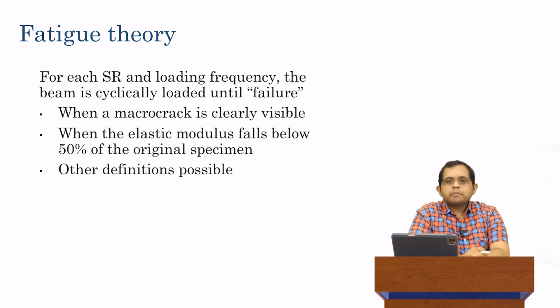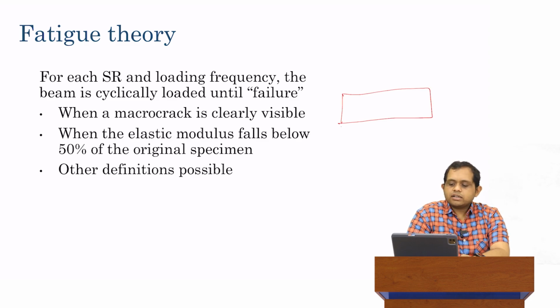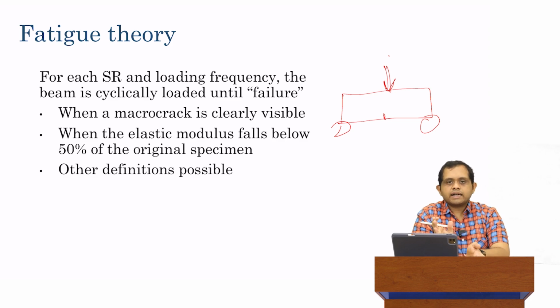Okay, now keep in mind, when we conduct a static load test, when do we stop the test? So when we had a static load test, and maybe you're doing a 3-point bending test, we basically increase the displacement and we measure the load until a crack just forms. Once a crack just forms, we stop the test. And I hope many of you have done the test in the lab, and your lab instructor would have shown you the crack, and it's a very clear crack that you can see forming.